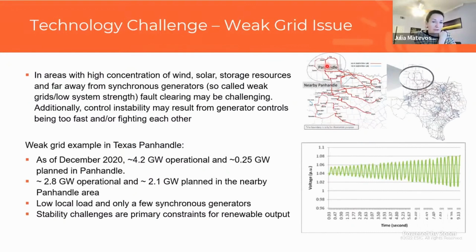But currently no, and they're also looking at using synchronous condensers to support the grid more beyond what they have. Currently they have 2. They are looking for more. One thing that underlines the urgency of having the computational burden resolved for EMT studies is that currently system operators are looking at synchronous condensers not only as a solution for technical issues, but also as a solution that allows them to continue using the simpler type of simulations that we're using today, like phasor domain simulations instead of EMT.